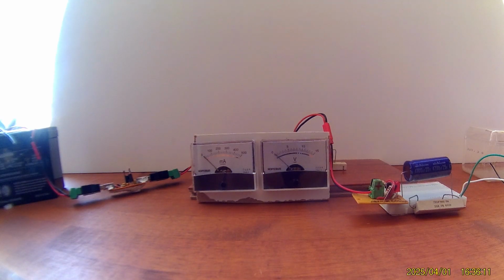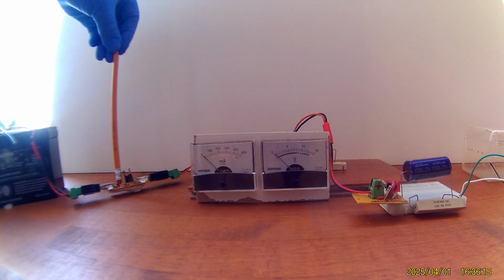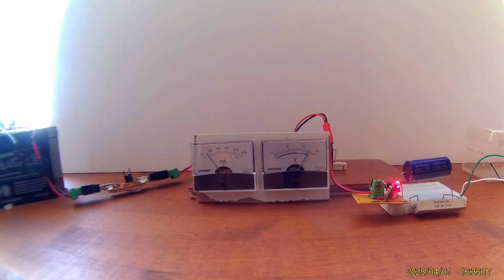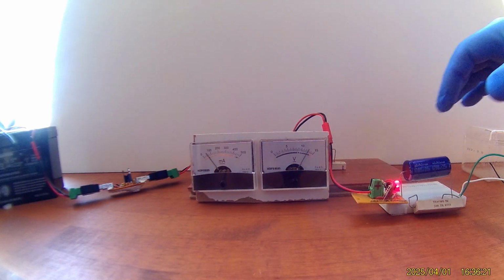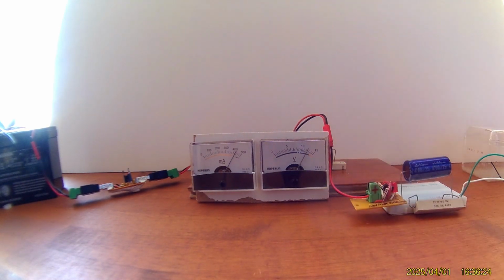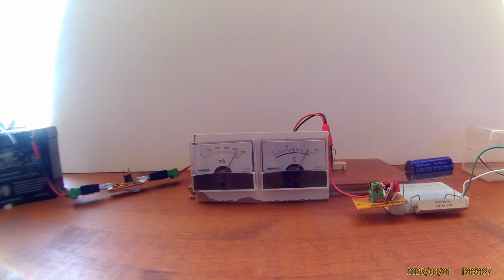Part 3 brought back the sense resistor to control the current limit, instead of using the base current and transistor beta gain to determine the collector current. The new design uses the VCE plus sense resistor voltage drop to target the collector current and corresponding load current